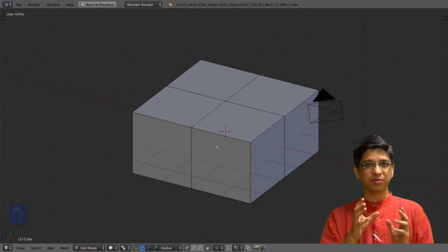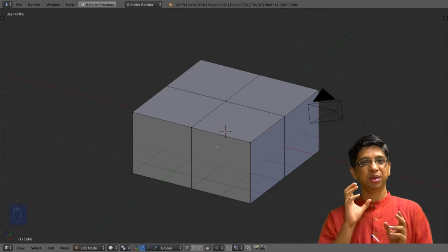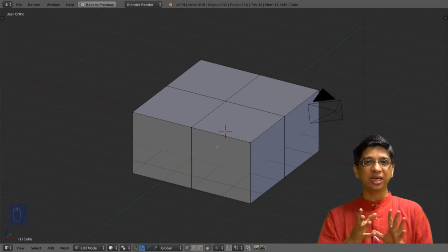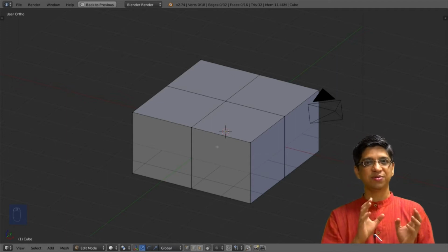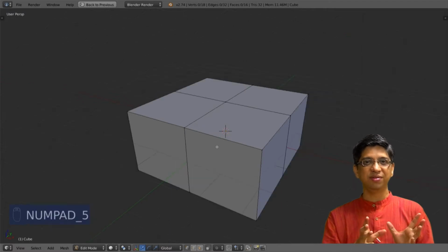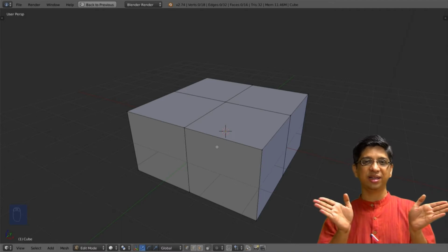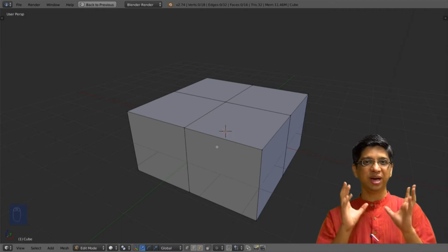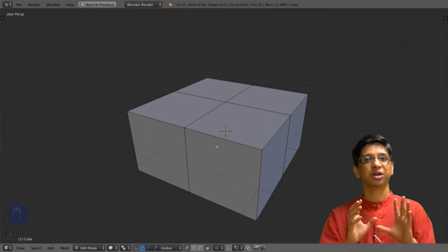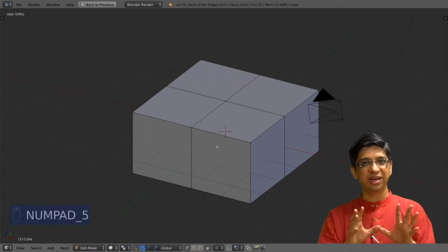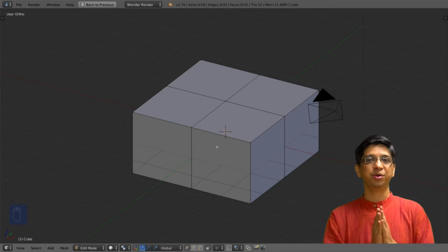We are in the orthographic view right now, and people who recall the toggle key for perspective and orthographic, it is 5. By pressing 5 you can see that this is perspective view, which has a slightly diminishing factor, but because we want to be correct in our modeling, let us use orthographic view. So, I will press 5 again and we are back to orthographic view.